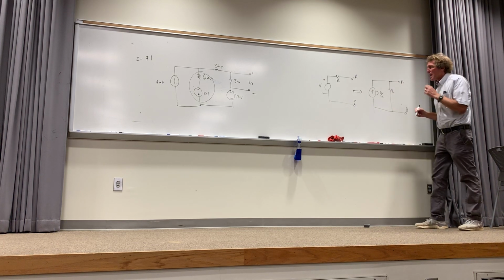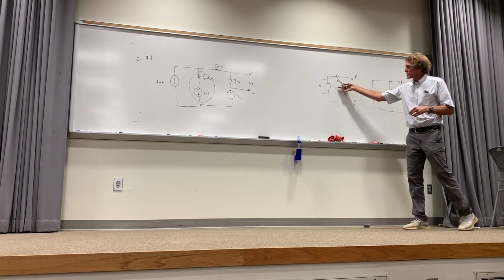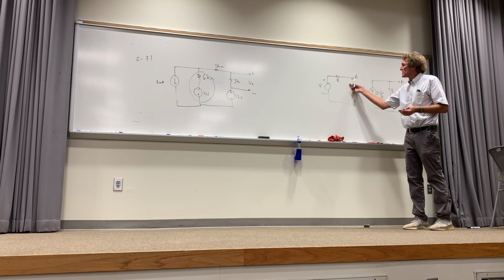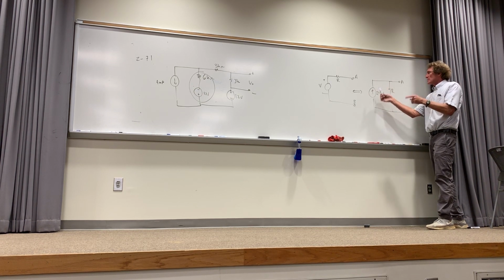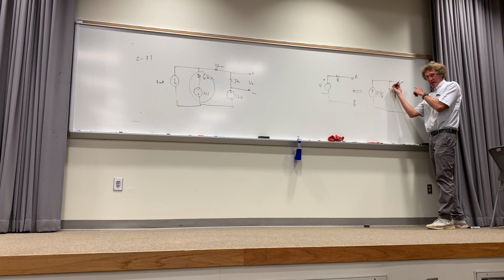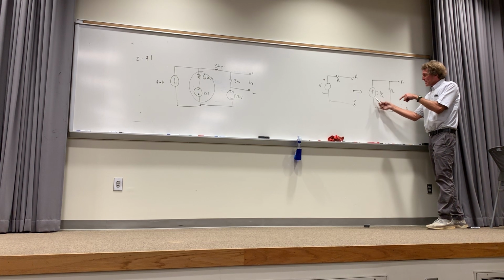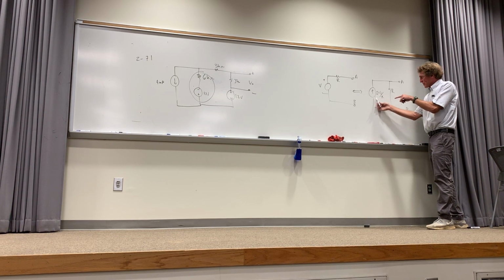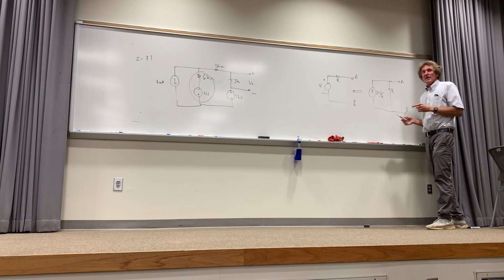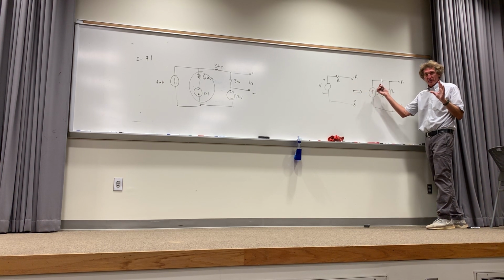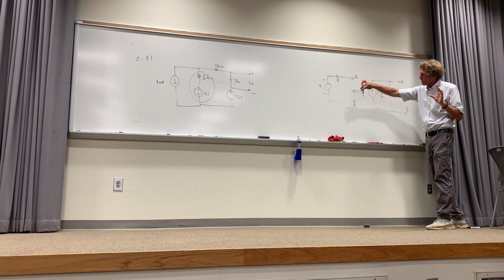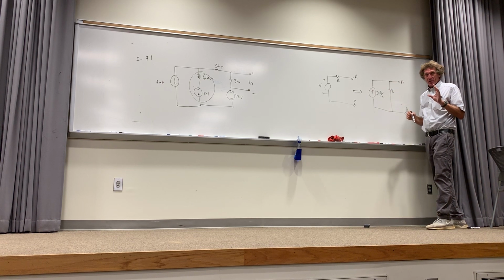You'll notice the polarity of the voltage source is, the positive is closest to A, it goes to one single resistance, right? Negative is closest to B. In this case, positive current flowing out and away goes to A. The negative, or from the negative terminal will go to B, or the current would be coming from B. Try to make sure you get this orientation right. Plus to minus, arrow up on this side. Follow me, class? Got to make sure you get that. Or if it was plus on the bottom, then the arrow here would be going that way. All right, make sure of that.